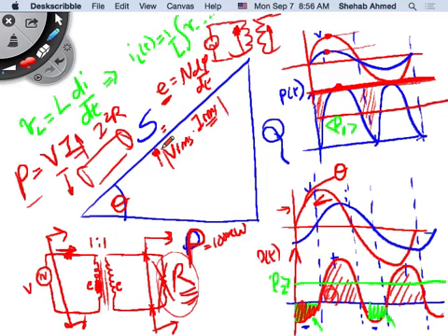So the power factor angle is an indication of how much reactive power you have in the system. Right? So now if you want to calculate your active power and reactive power from your apparent power or complex power, P equals what? S cosine theta, right? And Q is equal to S sine theta, right? Okay? Where theta is the angle between voltage and current. So this is very important. And one other consideration is the power triangle, that I know you took, but just out of review.